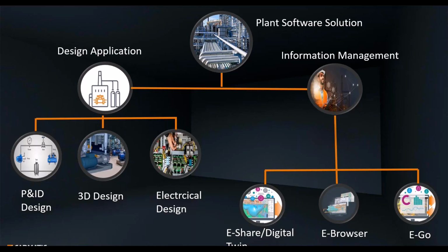This consistency check functionality in CADMATIC P&ID will help you to detect flow direction conflicts, nominal size differences, and missing position IDs, to rectify human errors in P&ID and to improve the quality. As well, you can import the DWG file in CADMATIC P&ID, and you can convert it into an intelligent P&ID. And again, when you export it, it will carry all the attribute information.